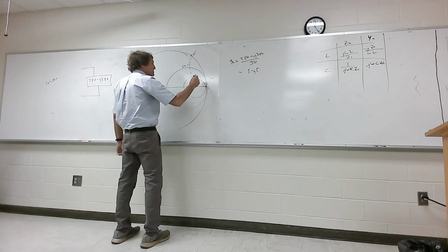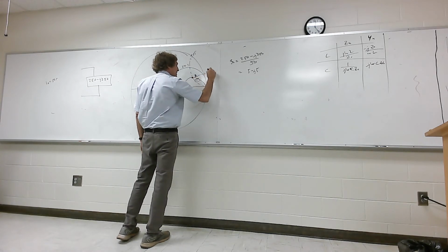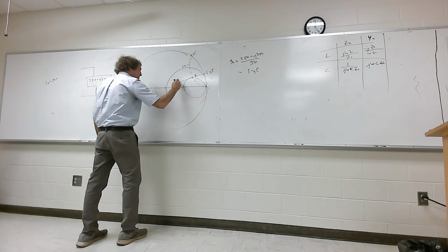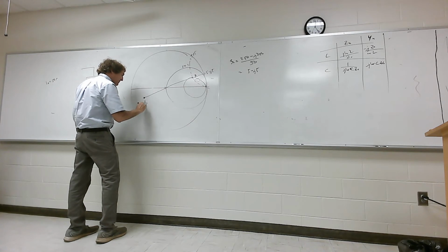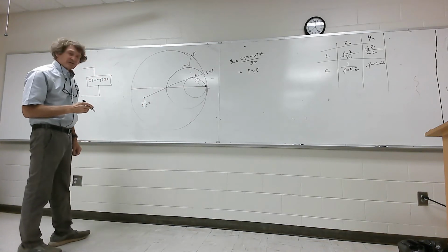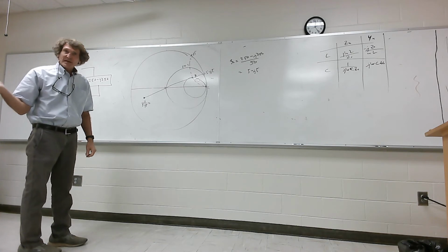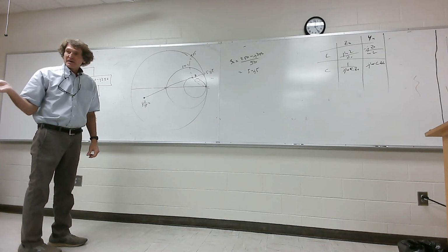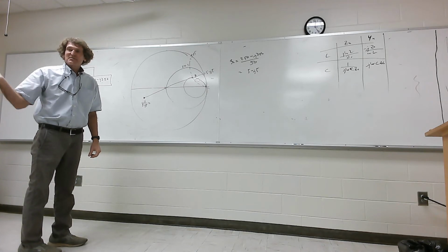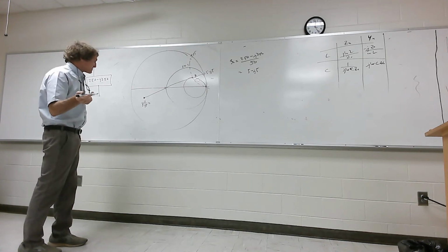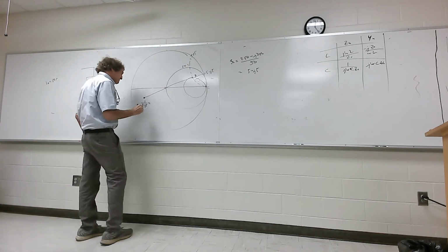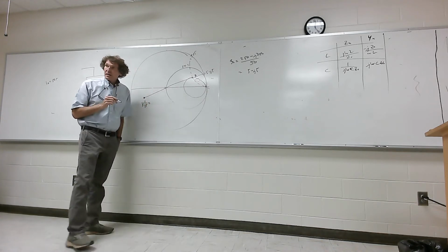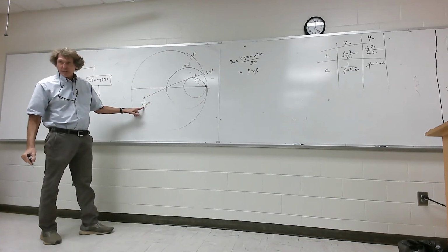So this was equal to 5 minus j5. We take 1 over that, and if you have your calculators, you can give me the exact value. And this is going to be 1 over 5 minus j5, which looks like 0.2 plus j0.2. You can correct me if I'm wrong. Is that what he has in his book? Just do it if you've got a calculator. I got 0.1 plus j0.1. There's 5 minus j5, right? So it's 0.1 plus j0.1 when you take 1 over that, right?